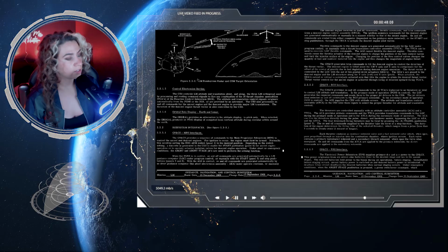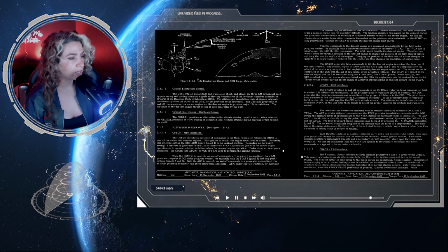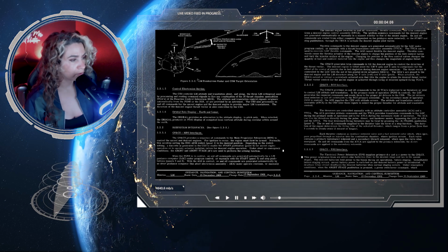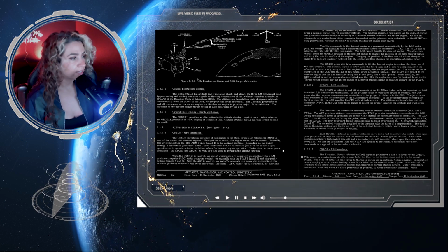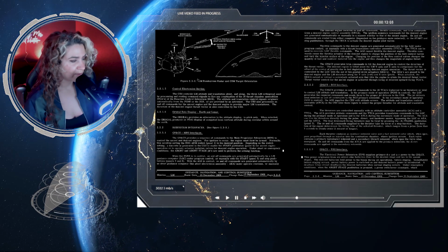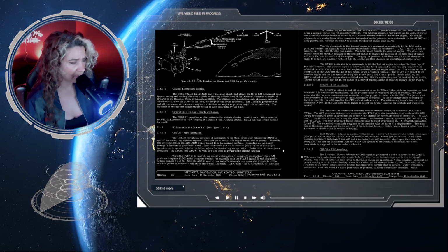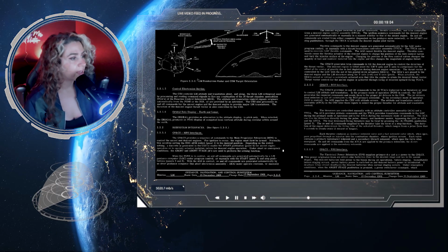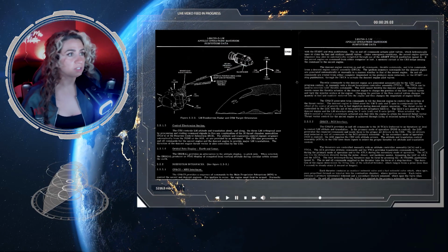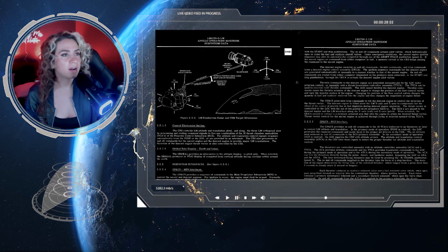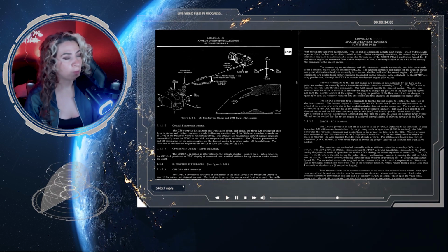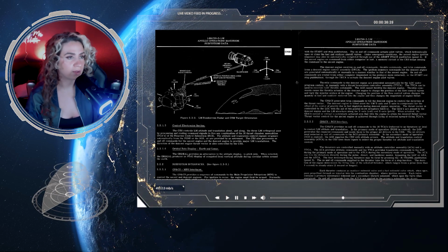When the PGNS is in control, on and off commands are generated automatically by the LM guidance computer, the LGC, under program control, or manually with the start, panel 5, and stop push buttons, panel 5 and 6. With the AGS in control, on and off commands are generated automatically by an abort guidance computer, the Abort Electronics Assembly, AEA, under specific routines, or manually with the start and stop push buttons. The on and off commands actuate pilot valves which hydraulically open and close the fuel oxidizer shutoff valves.